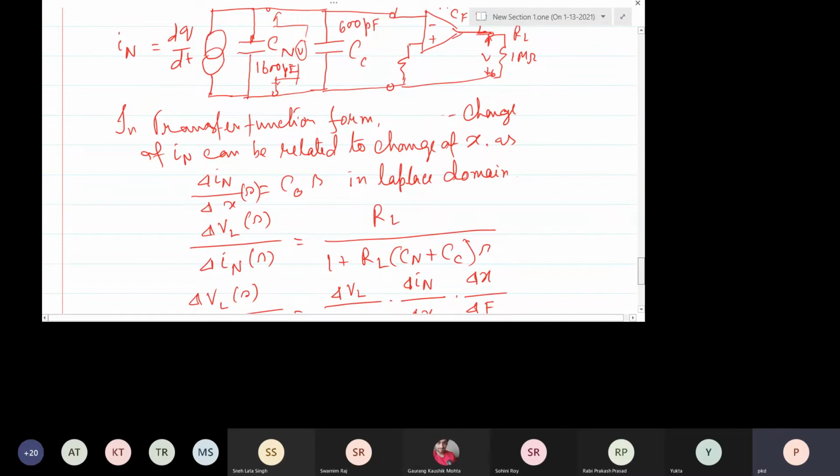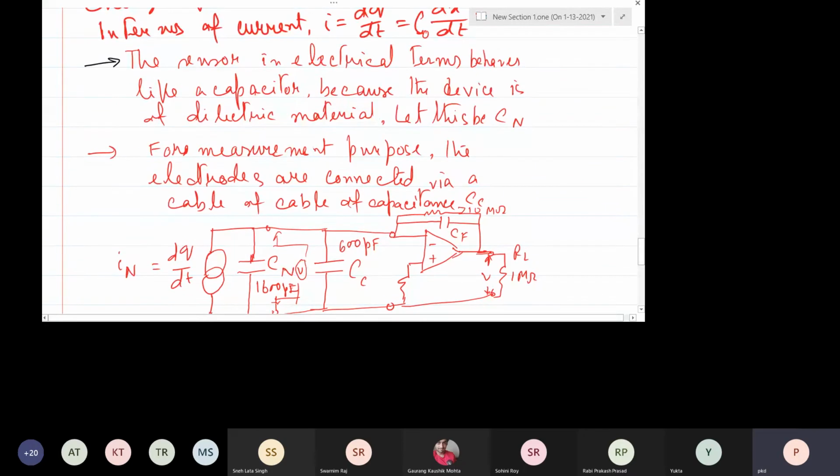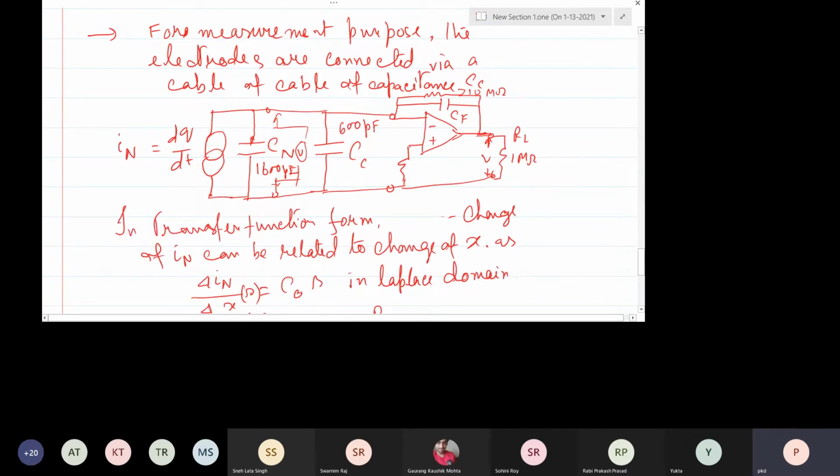Actually, if you consider that you can measure the ideal voltage across this capacitor, then there will be a DC response. Because if I drive a capacitor by a constant current source, what will happen? It will be a charge source. Because it is lossless, where will these charges go? They will go nowhere.